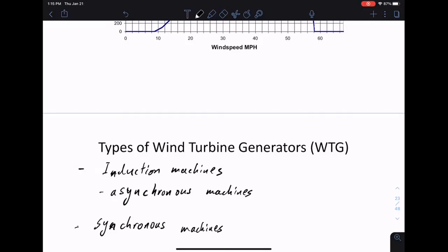That's why a lot of what we cover in 351 about induction motors applies directly here. It applies verbatim to generators because nothing changes in the circuit, except you flip a sign to change the machine from consuming power to generating power. Otherwise there's no difference. That's one thing to remember. That's why these are sometimes called machines.